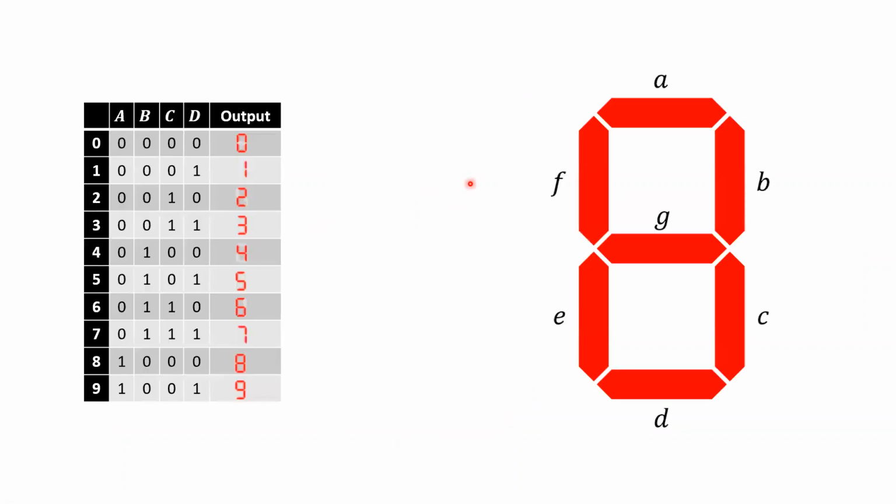If you look at the display, you can see it's got segments. It's actually got 7 of these segments. And basically, when we change the input, each of these segments will be either on or off, right? So either going to be 1 or 0. So the first thing that we can do is label these segments with lowercase letters. So A, B, C, D, E, F, and then we have G in the middle. Once we've done that, we're going to look at the inputs in more detail.